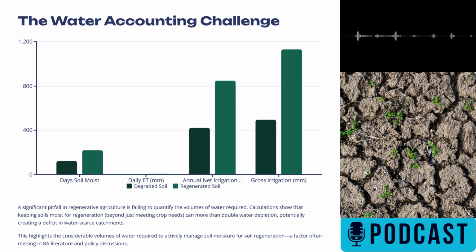Right, SIR. This is all about how quickly water from rain or irrigation can actually soak into the soil surface. And the structure of that very top layer, maybe the top centimeter or 2, maybe 5, that's absolutely critical here. Why the top bit specifically? Because that's the bottleneck. Imagine a less healthy soil. Maybe it's compacted from machinery or it forms a hard crust when it dries out. It might have very few of those larger pores, the macropores, that act like tiny tunnels for water to get in quickly. In that case, the base infiltration rate, the steady rate once the soil is wet, might be really low. Less than 5 millimeters per hour, maybe.